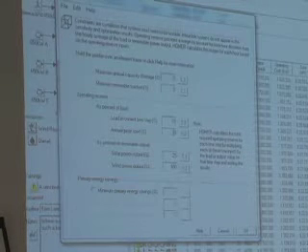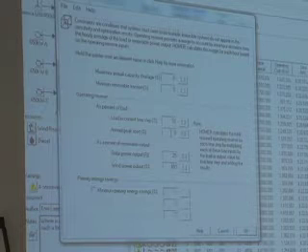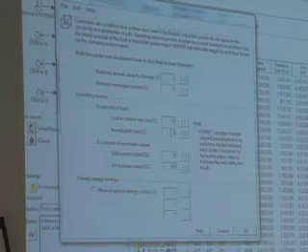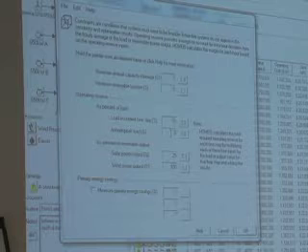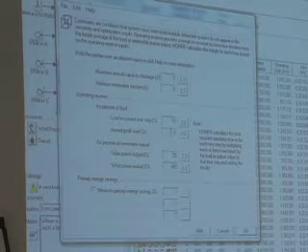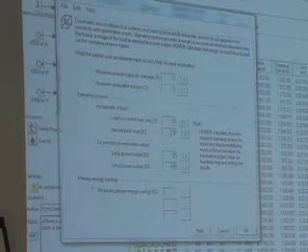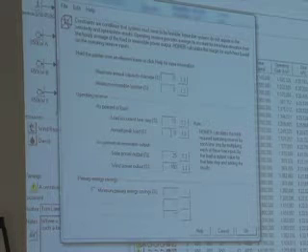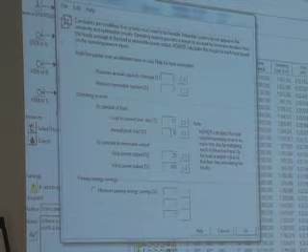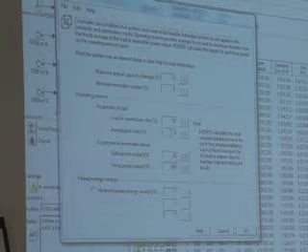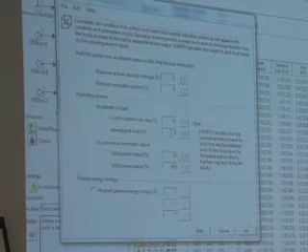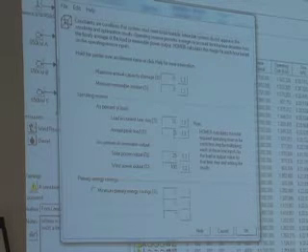You could think of this as just a certain amount of operating reserve in kilowatts. We could have specified it in kilowatts just as easily. We didn't, because if you want to do a sensitivity on the load growth, then this will scale with the load, whereas if we did it in kilowatts, it wouldn't scale with the load. So you should think of this as a sort of fixed number.